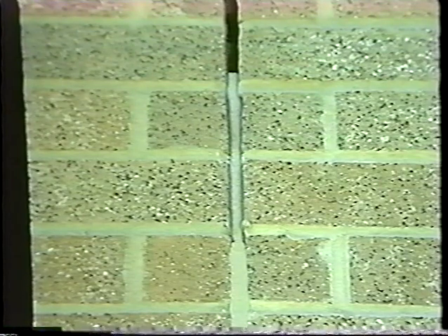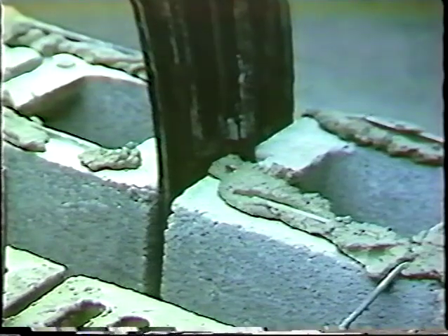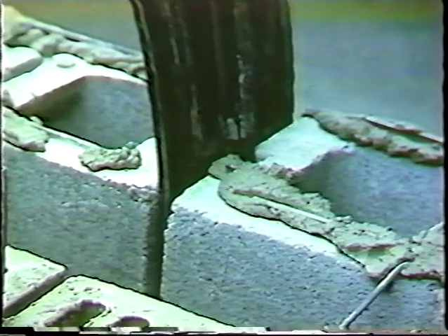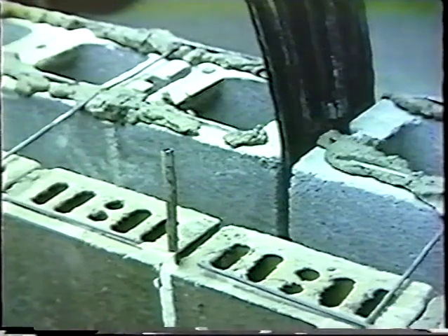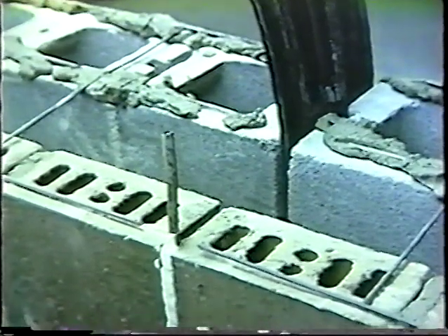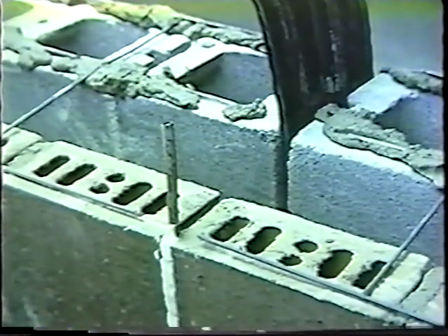Expansion joints, as the name implies, allow expansion to occur. They're used in brickwork and are filled with materials that can compress. Control joints, on the other hand, control the shrinkage of concrete and concrete masonry. They may be filled with hard materials, such as special hard rubber pads or mortar. Expansion joints and control joints are different and should not be used interchangeably.